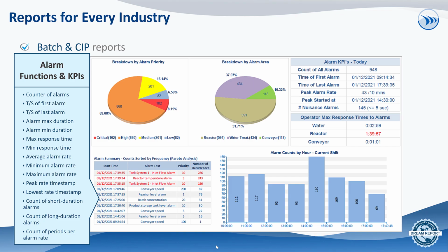Or maybe you want to look at rates of alarms and when are you getting floods? Is there a pattern that every Monday you're getting an excessive rate of alarms first thing on a Monday morning? Why is that? Very hard to make sense of your alarm and event data if you don't have metrics like this.